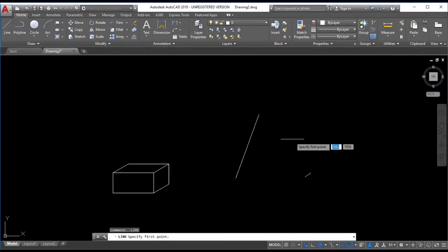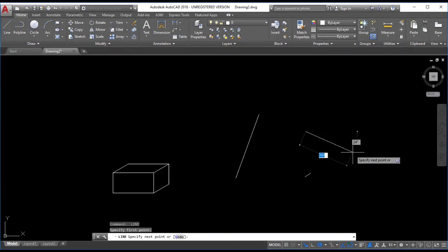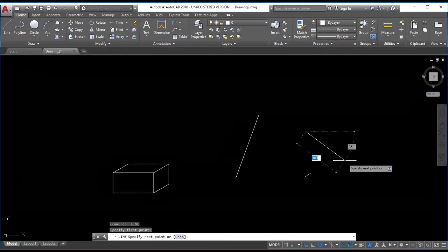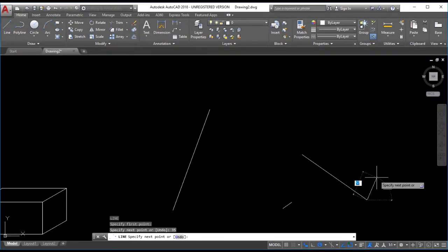If we reactivate the line command and we go below that green line, the x-axis, we are also able to type in the angle in relation to the x-axis up there. So we need to type in the angle first or the distance first, whichever you choose. So let's type in the distance first since it's there. So say 185, and then tab to the angle. We have it at a 15 degree angle right here. So I am going to type in 35 degrees, enter, escape.